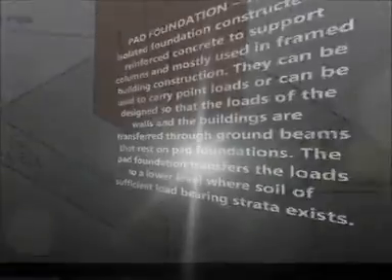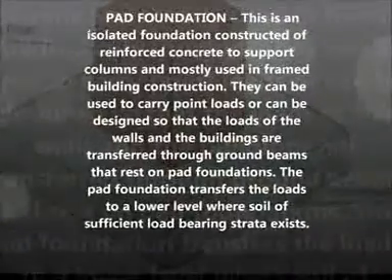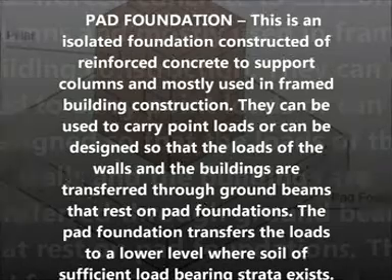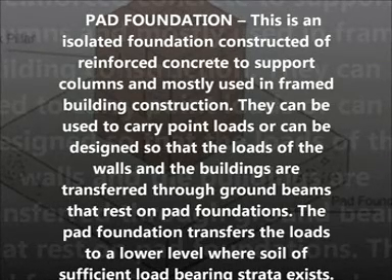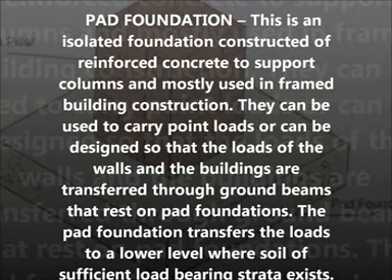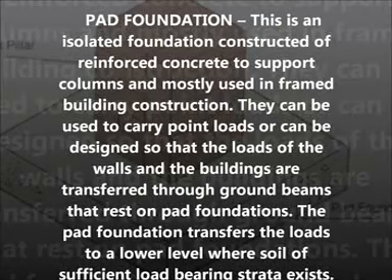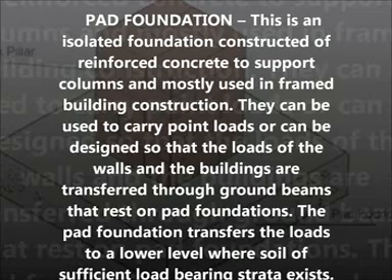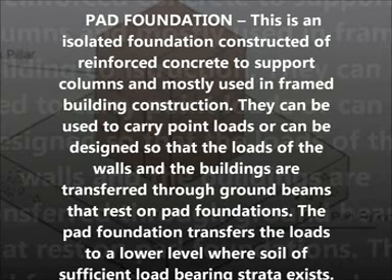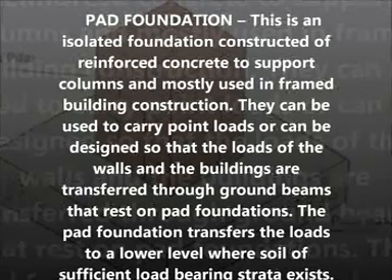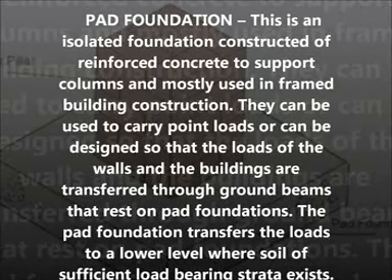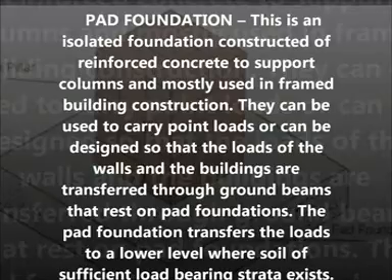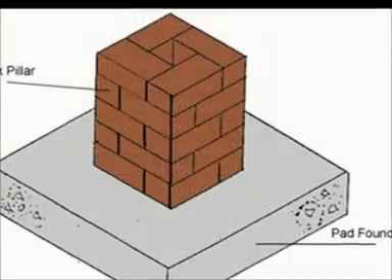Pad foundation. This is an isolated foundation constructed of reinforced concrete to support columns and mostly used in framed building construction. They can be used to carry point loads, or can be designed so that the loads of the walls and the buildings are transferred through ground beams that rest on pad foundations. The pad foundation transfers the loads to a lower level, where soil of sufficient load-bearing strata exists.